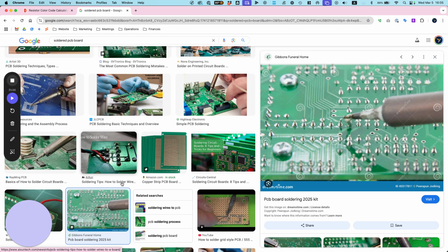So put my soldering iron at the joint. Oh, actually, I don't even need to put any. All I did was what we call reflow it. So I just heat up the joint and let the solder kind of flow around it again. All right, let me just show you. This is what it looks like now. You see that joint? This is ideal.